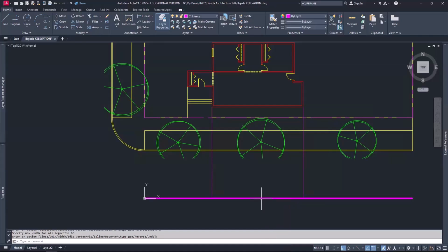All right. Next, my building height. I know that I decided to make my building 9 feet. But before I do that, I know that it's also raised 1 foot 6 inches because each one of these steps is a 6-inch step. So I need to elevate, or I need to put in that foundation. And that foundation pretty much is in the foreground right here. So here's what I'll do. I'm going to offset 1 foot 6 inches, enter. I'll select this polyline and I will offset it up and enter.